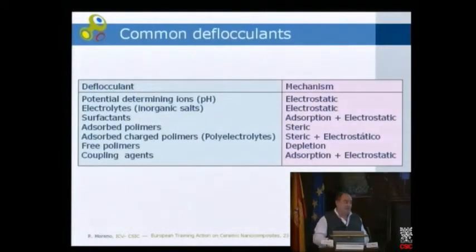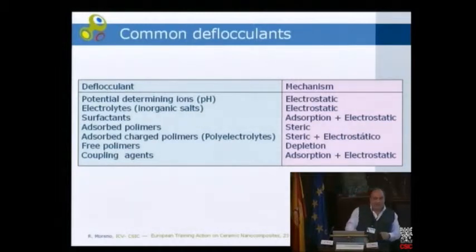In the case of electrostatic stabilization, we have the same. At short distances it is the steric effect which dominates, and at long distances the charges operate and introduce an electrostatic separation mechanism. So this is the advantage of the electrostatic mechanism, and this is the reason why they are the preferred substances to be added to the ceramic suspensions. In this case, we have charged polymers, which are the so-called polyelectrolytes.